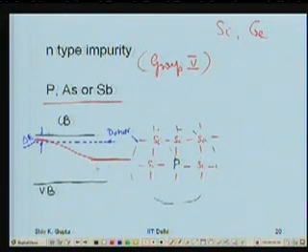What has happened at that temperature you have reached, I'll show you that. Now the temperature is enough for the electrons from here to get excited in large number to reach there. And this number becomes very small, meager, as compared to the ones which are coming from there. So it becomes an intrinsic conductor. Impurities have really no role to play after that. Impurities are playing a role at low temperatures only. So that's very high temperatures. This number will be so high that it will be overtaking these electrons which can be excited from here.